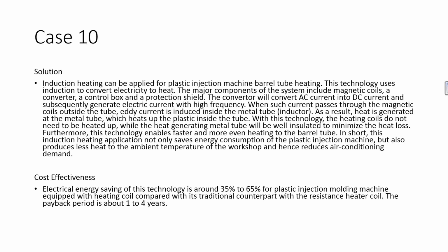When such current passes through the magnetic coil outside the tube, eddy current is induced inside the metal tube. As a result, heat is generated at the metal tube, which heats up the plastic inside the tube.